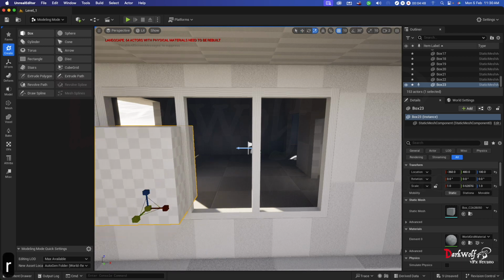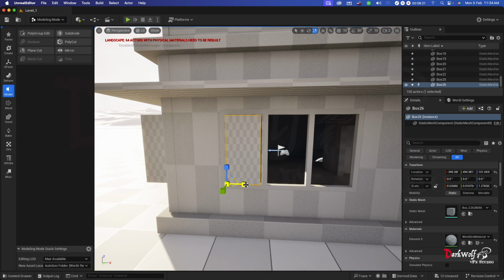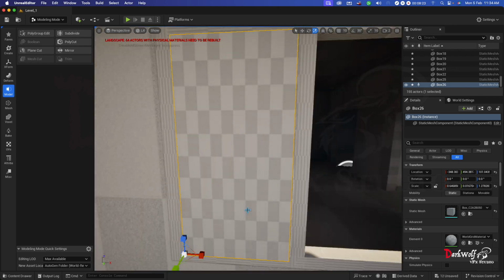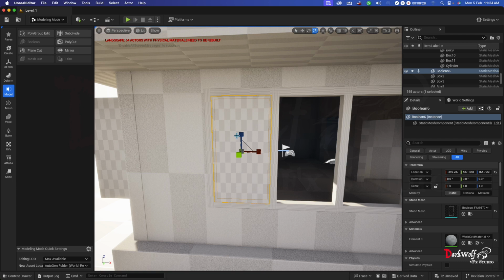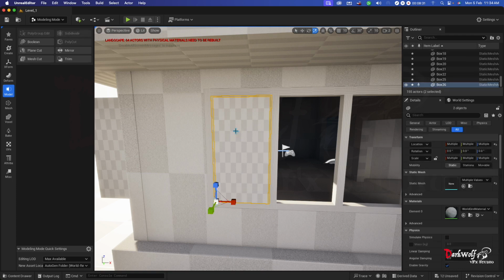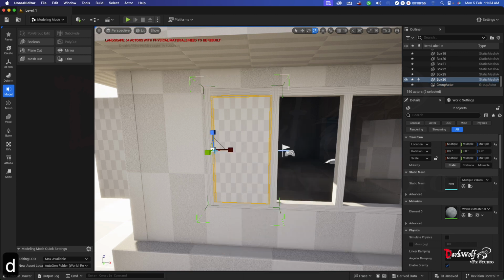For that, first create a door border, then add a glass in it. Here you can create two boxes, one larger and one inside that. Now apply boolean, as we already told you. Then add a piece to fill that hole. Now holding the shift key, select both the boxes. Now we can right click and select the option Group, or Command G is the shortcut. Now change the position of our pivot to a corner for opening inside to outside, just like this.